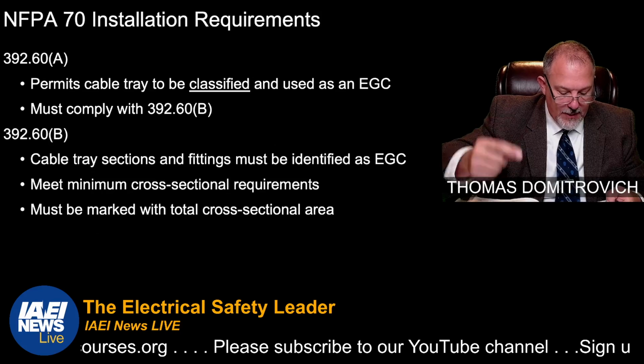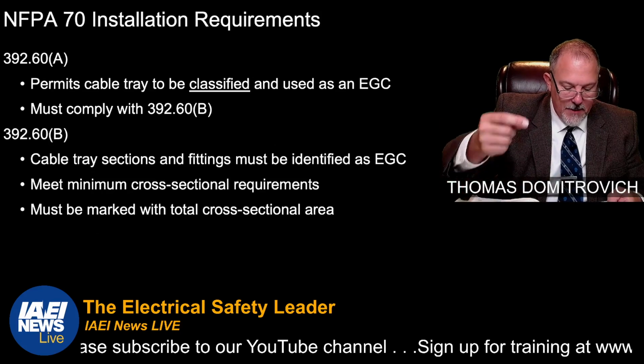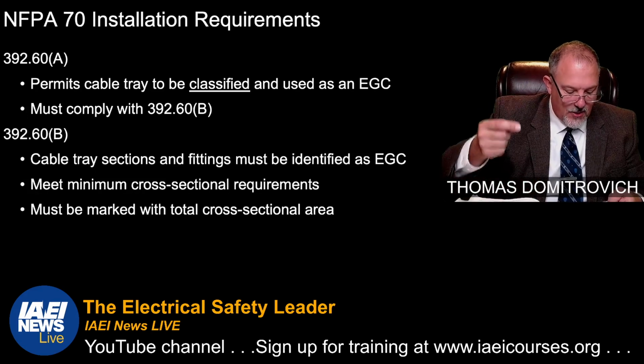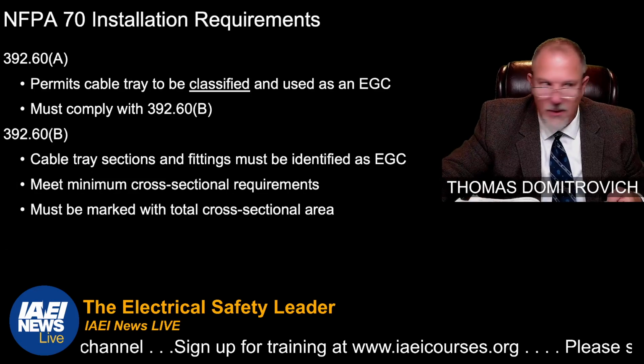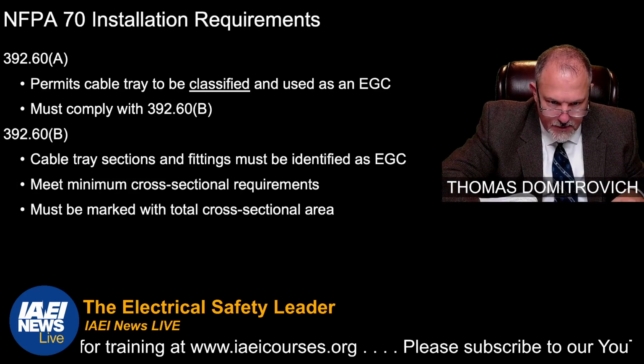Cable tray sections, fittings, and connected raceways are bonded in accordance with 250.96 using bolted mechanical connectors or bonding jumpers sized and installed in accordance with 250.102. So, what are we talking about there, Tom?